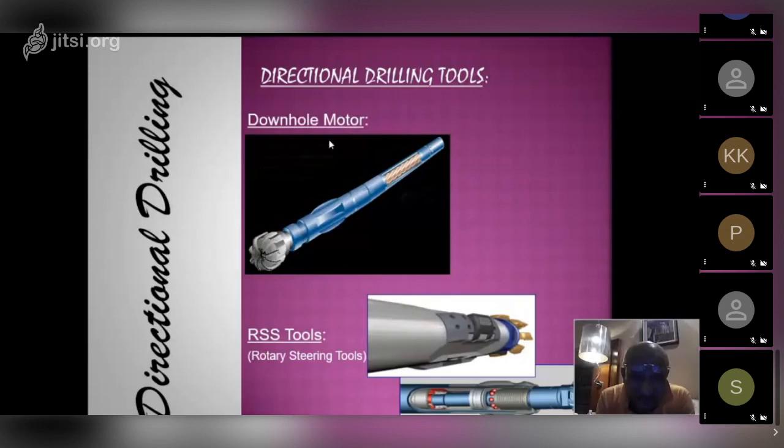Now there is something called a downhole motor. I was talking about the motor. This is a very conventional method of drilling a directional well. This is a motor which gives a direction. Basically, you see these lines here. These are the graduations on this motor. Once we set this, there are degrees written on this part and this part. So let's say 1 2 3 4, 1 2 3 4 is written, so we match 2 to 2 of this and 2 of this by screwing, unscrewing, and then a bend.